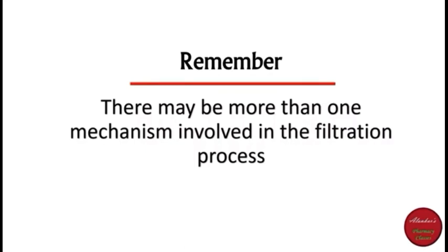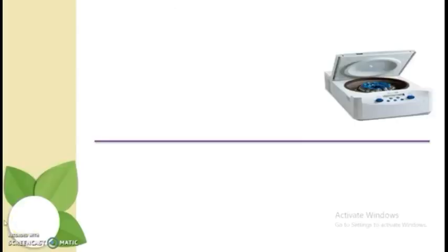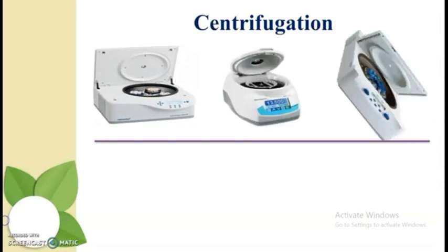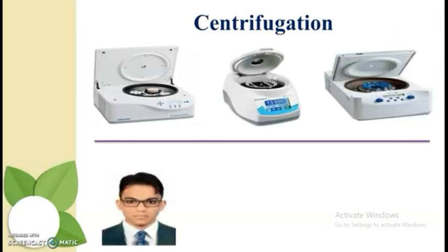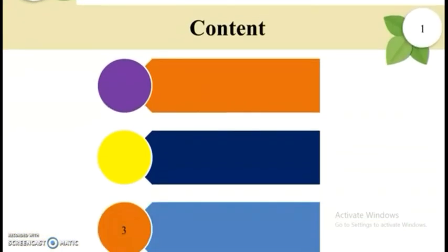Then the next equipment is the short cycle automated batch centrifuge, and the principle is filtration, and it is used for semi-continuous type. Then next one is the horizontal centrifuge, and the principle of the horizontal centrifuge is sedimentation, and it is used for slurries containing 0.5 to 50% of solids.